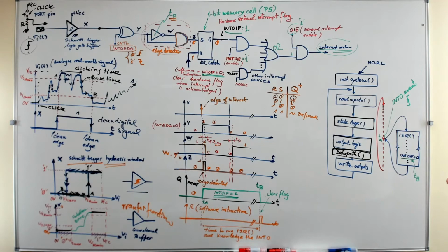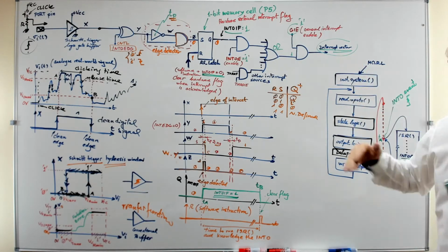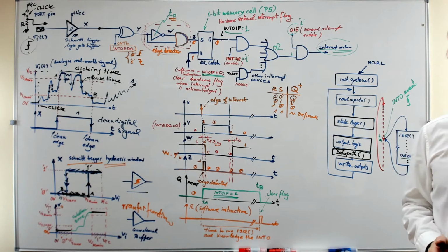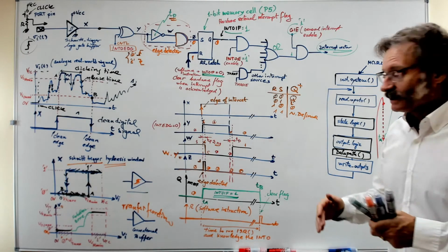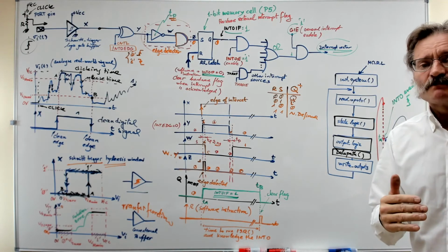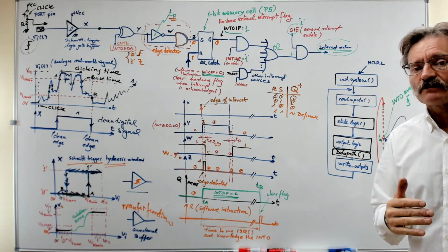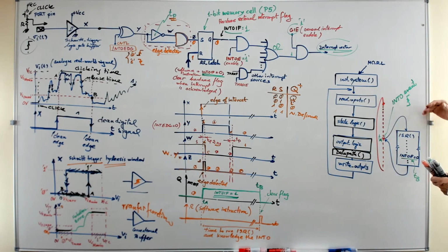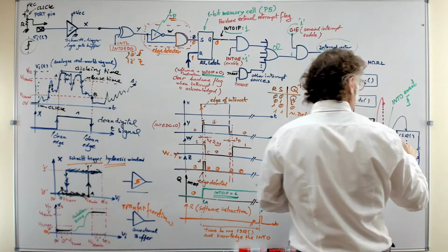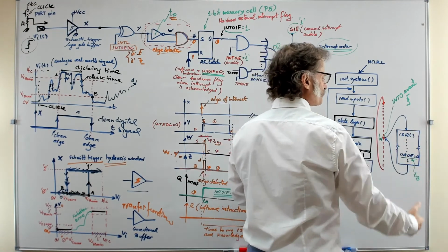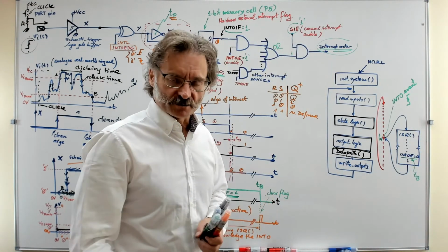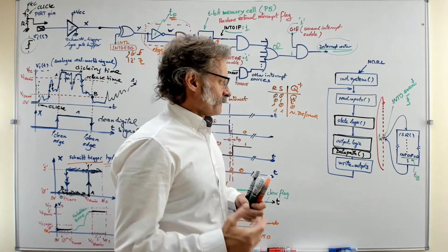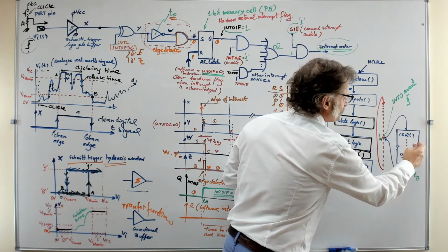And then what? Well, if you allow it to jump this way to the interrupt vector, the main program makes this kind of call to attend an interrupt and goes to another section of the code called the interrupt service routine, as you see here, where you have several instructions and several tasks to do.